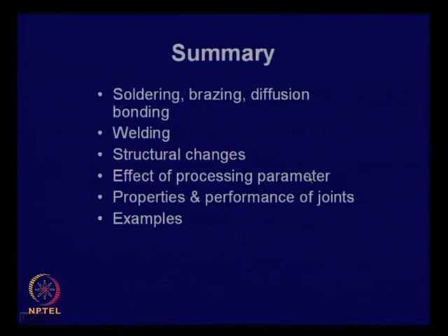Apart from thermophysical parameters, the dimension of the job is also important. The preheating, that is the temperature of the job, is also important. The speed at which you weld, the velocity of the weld and the heat source, also affects the structure. We talked about how it alters the shape, the temperature contours, and therefore the structure of the solidified metal, and all these will affect properties.